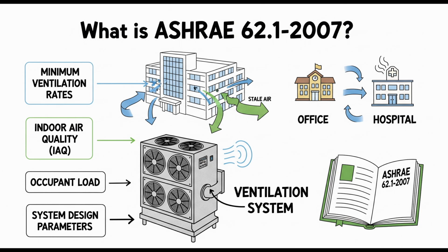Wow. Okay, this has been a really, really deep dive into ASHRAE 62.1-2007. Let's try to recap the big takeaways, the key insights. Acceptable indoor air quality. It's this blend of objective health protection, no harmful contaminants, and subjective human comfort, keeping most people satisfied. Right, and it all starts with looking at the air outside the building first and being careful about where you bring it in, avoiding those local pollution sources. Then the system design itself is critical. The materials air touches shouldn't grow mold or fall apart. You need filters, you need humidity control in some cases, and crucially, you need access to maintain everything.